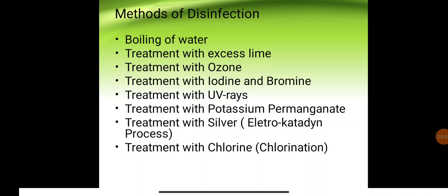The disadvantages are, it is more costly than chlorine. The chlorine method is the common method of using a disinfectant. Compared to chlorination, ozone is costlier, and it does not create a disinfectant residual. That is the residual which is left in the water, and that is not there in the ozone type of treatment.